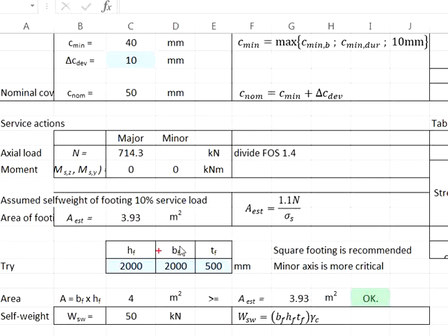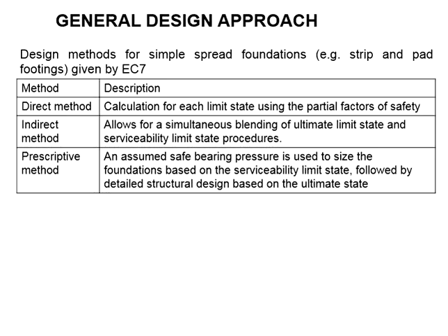Next, we will need to propose a suitable size for the pad footing. Bear in mind that we are designing the foundations based on the prescriptive methods. It means that when we need to estimate the size of the foundations, it will be based on the serviceability limit state. And then when it comes to the structural design, only then we use the ultimate limit state.